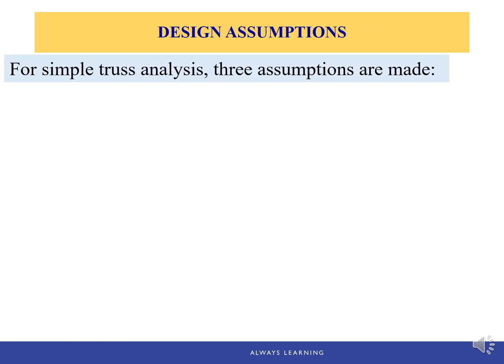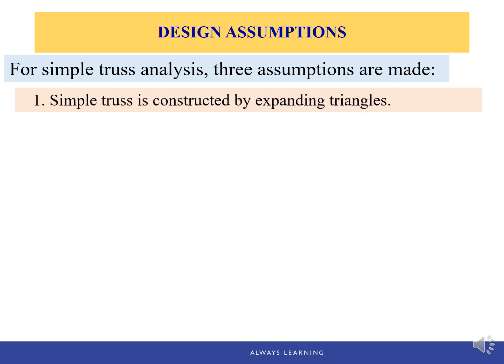For simple truss analysis, three assumptions are made. First, simple truss is constructed by expanding triangles. And in fact, in this class, we further limit to 2D truss structures. Once you've learned this, you can expand the application to space truss or other 3D truss structures.